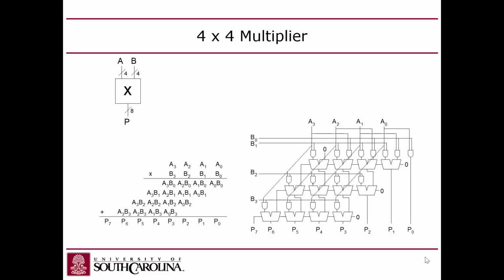But they used a full adder, so one of the inputs is a 0, but they're still adding 2 bits together to produce a single bit output. And then they still have to have a carry out that carries out from A3, from this column to this column. Make sense?